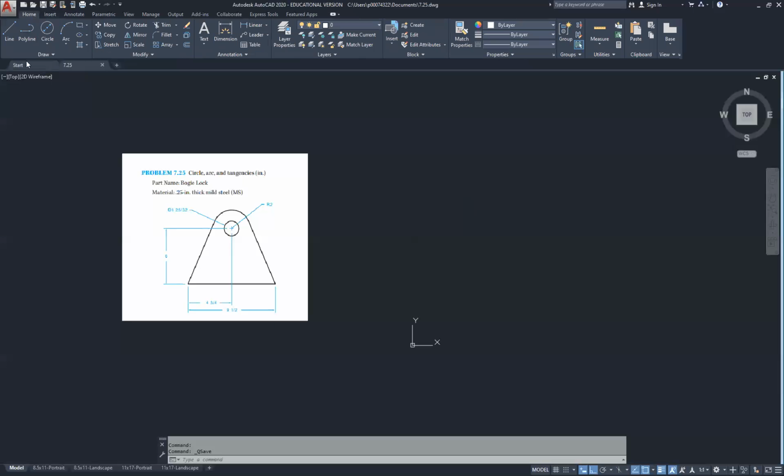All right, let's go ahead and start with our drawing. Start at the Home tab with the line command. Point it across. Now, to type this in, it's very important when you're typing in a fraction. Type in your whole number, which in this case is 9. Then you can use the little negative, typically referred to as a dash. Okay, and then the fraction.